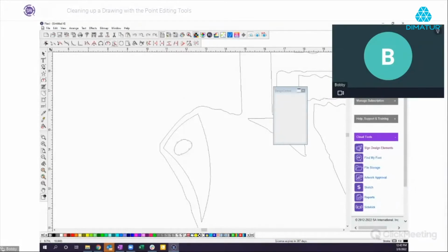Now, these two here, I don't use as much. They're just not quite as easy to control. So this one right here is optimized by smooth arc. When you click here and then click here, it just gives you this smooth arc, and it's going to smooth it out for you. It doesn't let you actually control anything, but you can run along the arc to get it to where you want it to be.